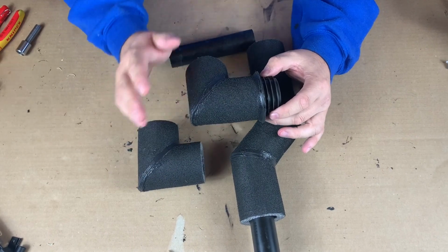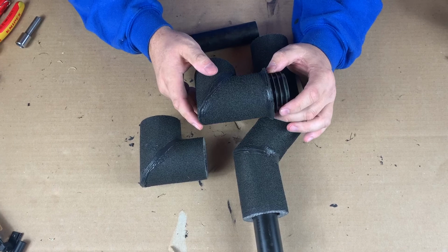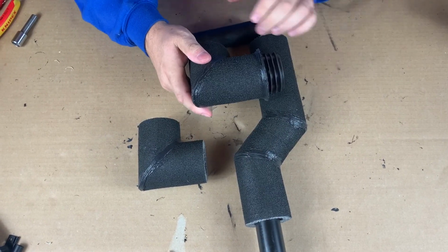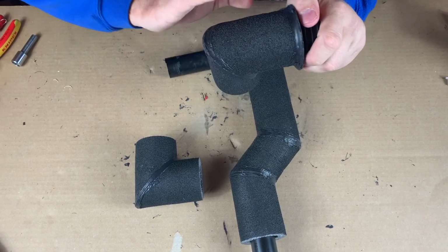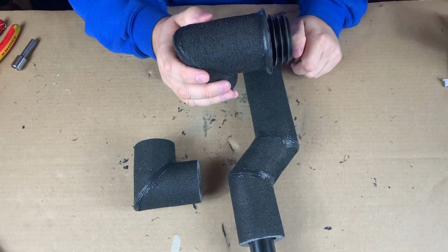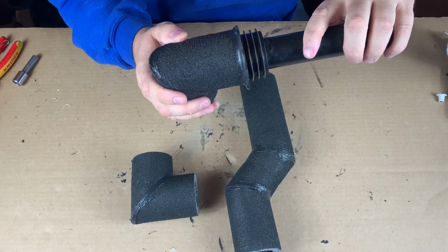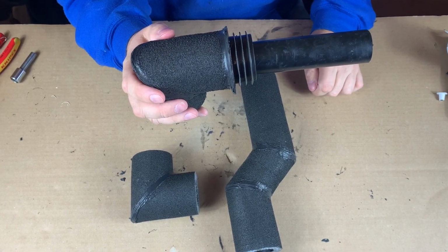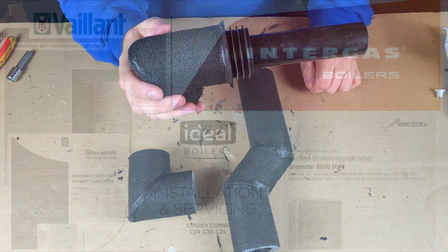So just to cover, Condensate Pro covers all the British Standard 6798 regulations. Sealing with the bond and seal is correct. This then goes into the building with the pipe snug, and that seals up correctly. That seals into the wall, and then you take 1.25 inch, 32mm all the way through. So that covers all the regulations for British Standard 6798.